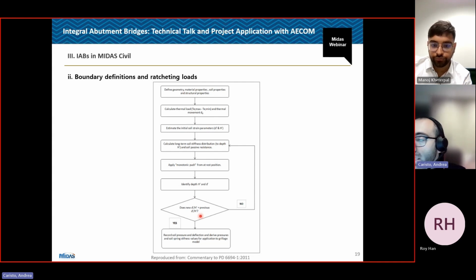And this allows us to get consistent pressure and displacement in the soil. What we get out of it is effectively a distribution of pressure. That will be our K-star pressure. And we can also read the stiffness below that point. So below H mark, where our K star meets K0, we're going to use distributed springs in our pile. And above that point, we're going to use the distributed pressure that we read from GTS NX, and we need to input that behind our pile.